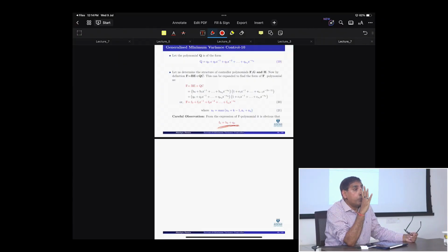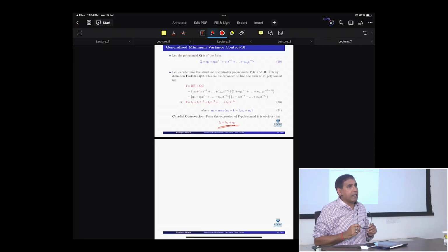No, a pole zero cancellation type controller should not be used under any circumstances. Under any circumstances, do not use any pole zero cancellation controller, because it has nothing to do with the system. Because you are defining your poles and zeros based on a transfer function. The transfer function model has poles and zeros, you see it. But imperfections must be there. So don't do pole zero cancellations. I will always advise, don't do that.